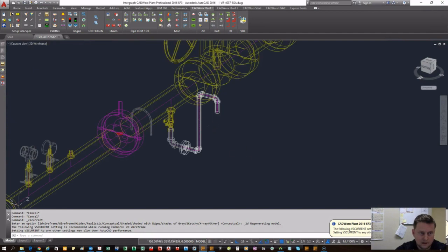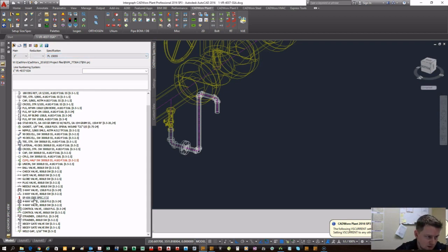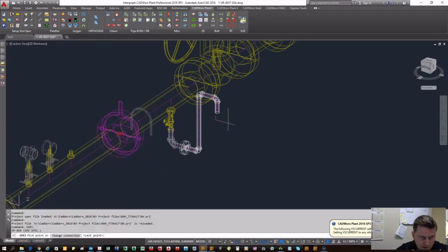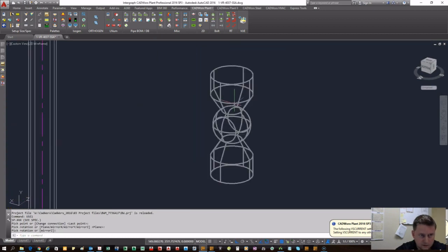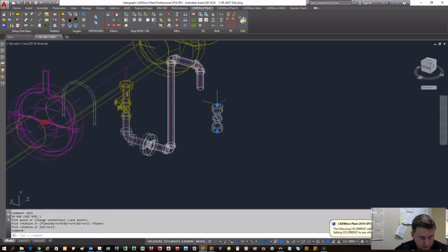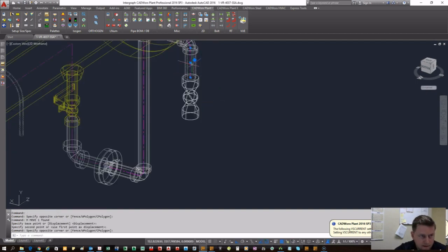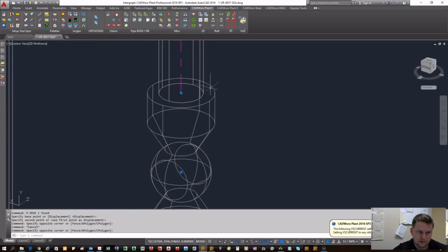Okay. We're back in our first piping drawing. Now the component won't automatically generate here. You need to refresh to make sure you're really getting the live data. So refresh your spec, and make sure you're still running on the same size and specification. We're going to click here. And there we go. There's our intelligent user-created component, SPXXX. We can go ahead and move that right to our piping. As you can see, we're not seeing the cross show up, so that is live and